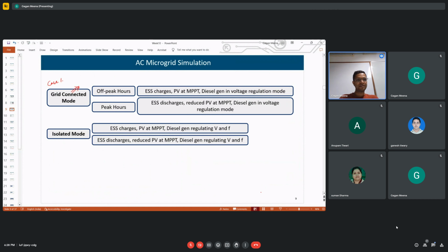Current will increase to a very high level and voltage will reduce, whether it is any kind of fault, LG, double LG, triple LG or LL. So if reactive power support is more, then voltage can quickly build up. If a good amount of reactive power reserve is there, post-fault voltage recovery time will be reduced, and that is to be ensured by all these available compensating devices, voltage regulating devices.